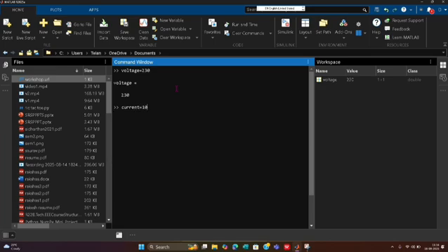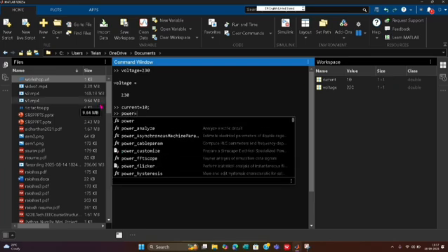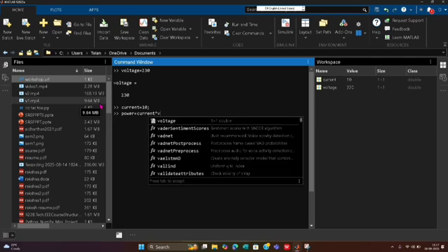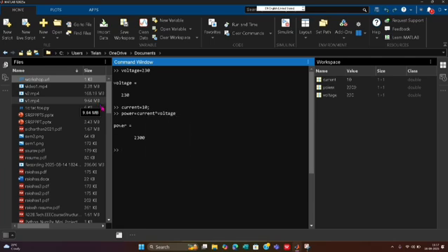and I am creating another variable current and assigning it the value of 10, and as you can see I have ended it with the semicolon, so it is not displayed again, and this current value is stored here in the workspace. Current with the value of 10 also has size 1 cross 1, and I can perform any mathematical operation, such as calculating the power. As we know, the formula for calculating the power is voltage into current. It is showing 2300, which is the value of power, and its value is updated in the workspace.